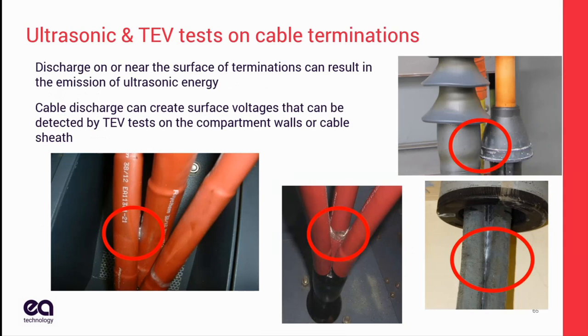We talked about surface discharge. You do have a lot of surface discharge in terminations. If you have unshielded cables or you have termination issues, here in the lower right appears to be unshielded cables. This white powder is PD. Here they have shielded cables, but above the shield they've got it too close together in a trifurcated cable. Same with the picture on the left.